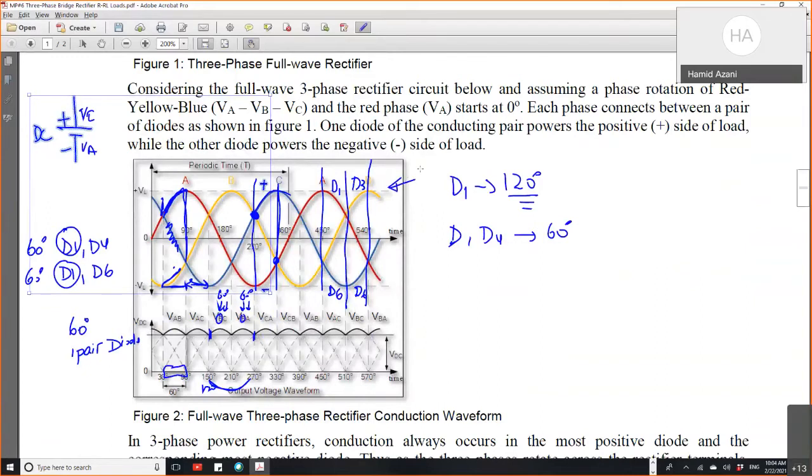That's why you can see here those curves are phase VA only, reference to neutral. These are phase signals, not phase-to-phase. Those ones are phase-to-phase: VA, VB, VB, VC, and so on. That's why here we see 3 of them, but here we see double of them, like 6 in each period.